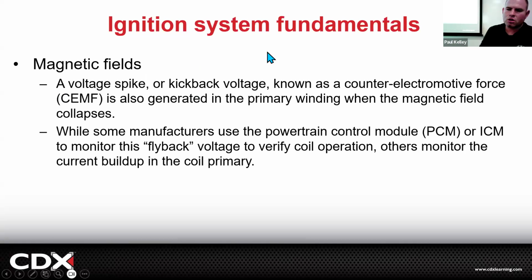Cool. And then just as a note, depending on the manufacturer, some of them monitor the flyback voltage to verify the coil operation. Other ones verify the current buildup. Some of them even check the ionization in the combustion chamber, right? So there are different ways to monitor this.